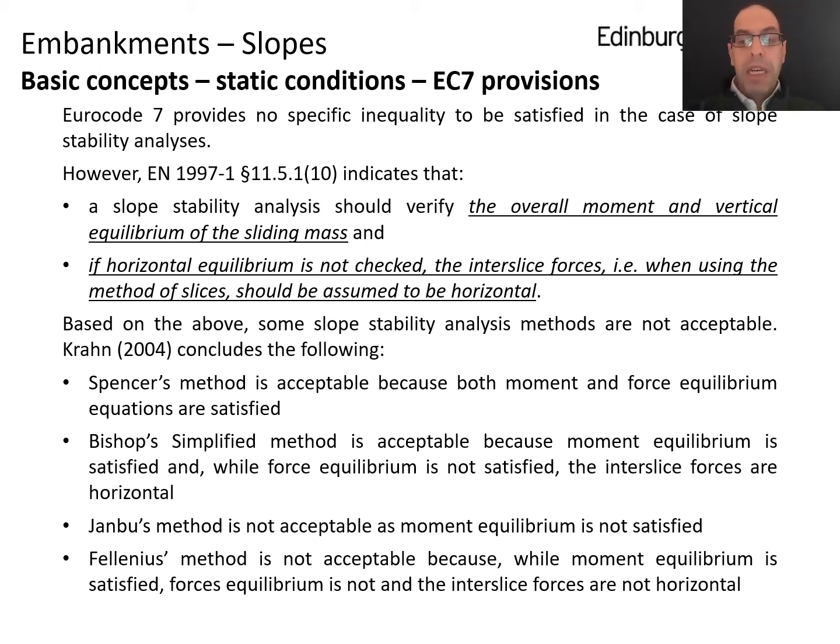Well, the standard is actually telling you what assumptions you have to take to use the method of slices, or in other words, it is telling you which methods of slices you can use and which ones you may not use. And that is summarized by people like Craig or by Orr in many publications. And what that translates to is things like Spencer's method being acceptable because the assumptions that it uses include moment and force equilibrium.